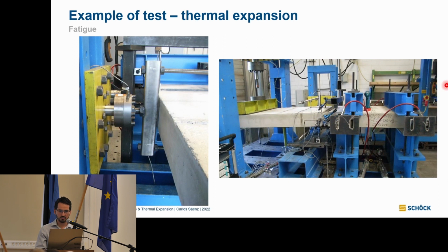Here we have more pictures of our horizontal press, and on the other side we see a test already done. You get to see the balcony already failed. So this is what we do. We have the inner slab, for example, and here is the Isocorp, already failed because we applied the cycles, and at the end we applied the force.